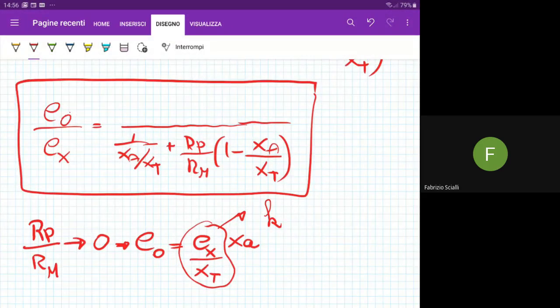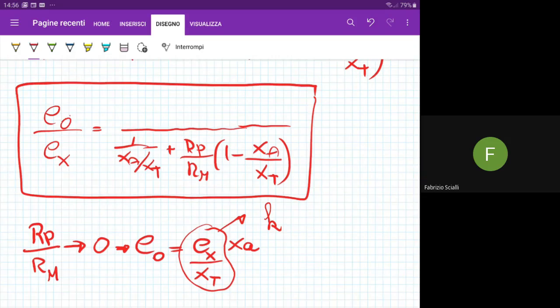Using such a transducer in that condition is very difficult. You would like not to have these operating conditions. Why? Because there is a non-linear relation between what you are measuring and the objective of that measurement. And if that depends on the actual measuring that is unknown, then you are in trouble. That's the reason why we prefer to have linear relations, so that you can skip the operating condition, the reference value, because it is practically the same.